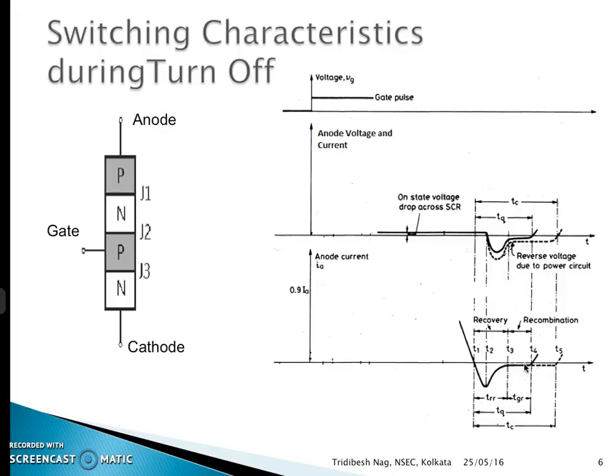The thyristor turn-off time TQ is in the range of 3 to 100 microseconds. The turn-off time is influenced by the magnitude of the forward current, dI/dt at the instant of commutation, and the junction temperature. An increase in the magnitude of these factors increases the thyristor turn-off time. If the value of the forward current before the commutation is high, trapped charges around junction J2 are more. So, the thyristor turn-off time TQ is applicable to an individual SCR.